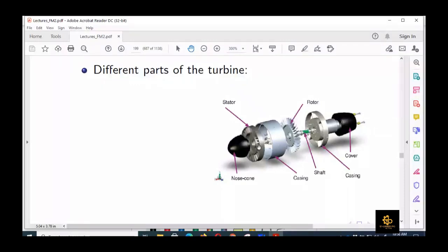But these rotor blades are attached to the rotating shaft, and when the fluid passes through the stator blade and then strikes the rotor blade, it changes direction as well as pressure, depending upon the angle of that collision with the rotor blade. It also imparts some rotational energy on this blade.